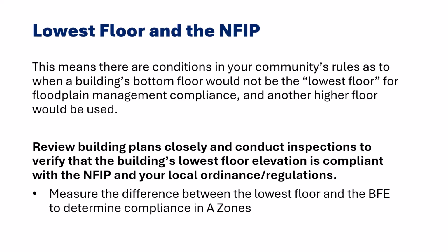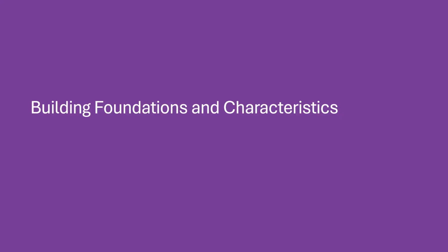Review building plans closely and conduct inspections to verify the building's lowest floor elevation complies with the NFIP and your locally adopted floodplain management rules. You'll need to compare the difference between the building's floors and the base flood elevation to determine this compliance. To help you connect information about a building to the BFE and the lowest floor rule sets, we'll start by talking about building foundations and characteristics. We'll talk about elevation certificate forms and show comparisons and scenarios about the building's lowest floor.